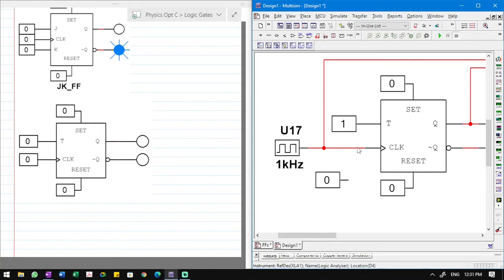How does the clock control the output? Exactly as we described before, the clock toggles the outputs whenever it goes through a rising edge. So it's a rising edge triggered flip-flop in this case. Now, there's something I did not mention before, but it's more appropriate to mention now. The JK flip-flop, and of course the T flip-flop, which is a derivation of the JK flip-flop, are what you call triggered bistables, in that they have two stable output states.